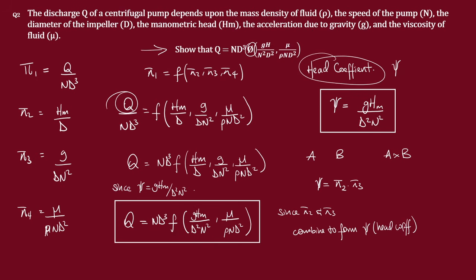So no matter how daunting this proof may look if you first encounter it, you just have to be calm and take the steps you're used to, the steps that we've established when covering Buckingham's Pi method. If you have a constant that you're not familiar with, it's perfectly fine to leave your solution in the natural way it ends up, even with Buckingham's Pi. So let's say pi of k is mu over rho VL. If we were solving a problem and we ended up with something like this, we could leave it the way it is and it would be perfectly correct.